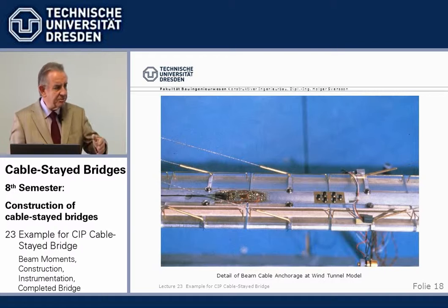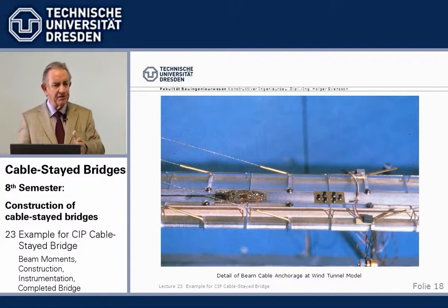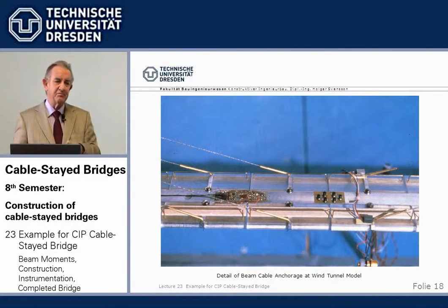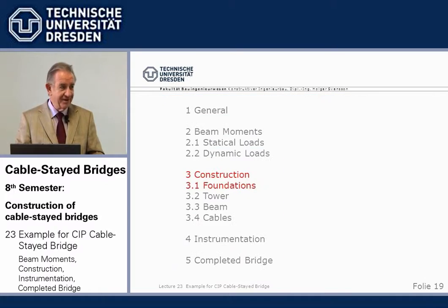buffeting, which means the wind which has different velocity, and we have the gusts, they bang against the beam sometimes in period. That's the governing loading, not aerodynamic instabilities. But it was the important investigation for the bridge. I can tell you, it's a 220-meter free cantilever, 1.2 meter high, in very high storms. But it worked. So what?